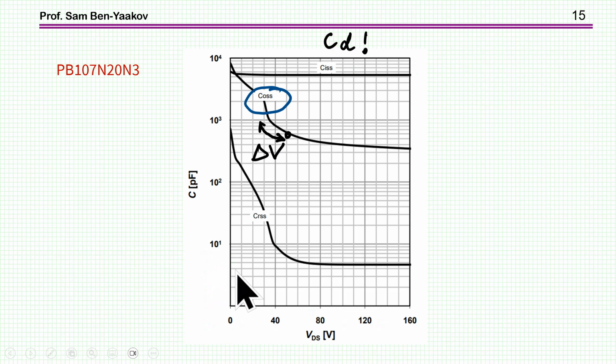considering the fact that we are talking about a non-linear capacitor. And when you have a non-linear capacitor, you are sort of moving over this curve. This is the C out SS, this is the output capacitance, but this is small signal. That is, it is measured by actually biasing the transistor and exposing it to a small signal.